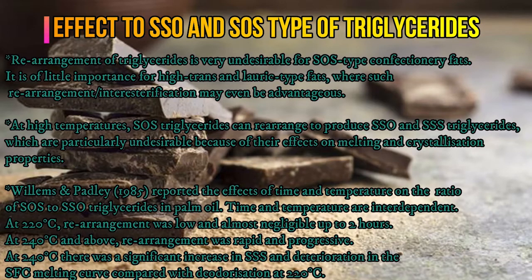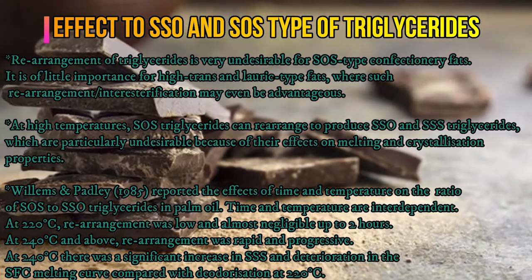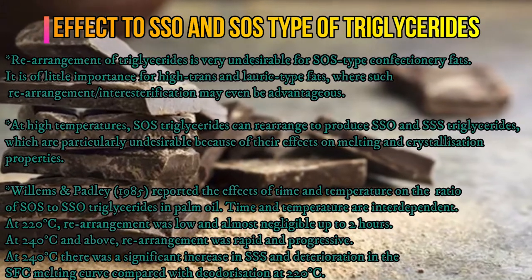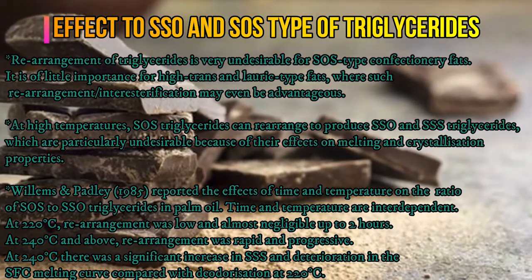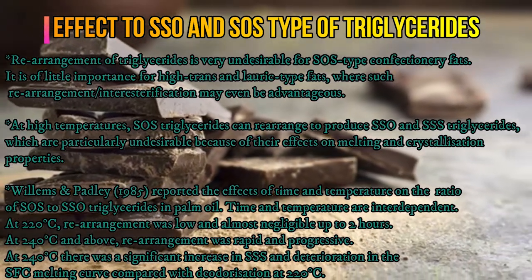At 220 degrees Celsius, the rearrangement was low and almost negligible up to 2 hours. At 240 degrees Celsius and above, the rearrangement was rapid and progressive. There was a significant increase in SSS and deterioration in the SFC melting curve compared with deodorization at 220 degrees Celsius.